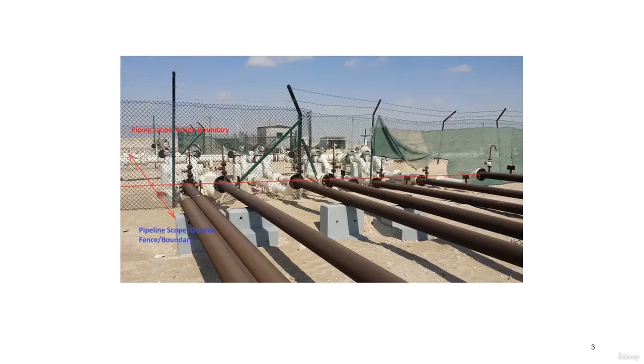and the actual demarcation you have to find from the process P&ID, means piping and instrumentation diagram. So in those P&IDs, they will be specifically marking from where the actual code break, means B31.3 versus B31.4 or B31.8, happens. So based on that, you have to use the design code in your stress analysis system, if your system consists of both B31.3 as well as B31.4 or B31.8 scope.